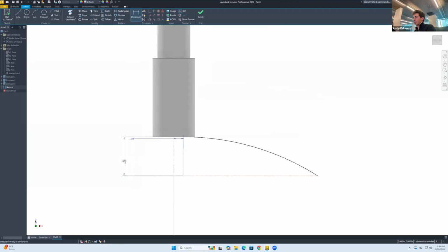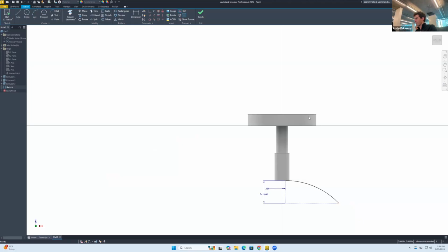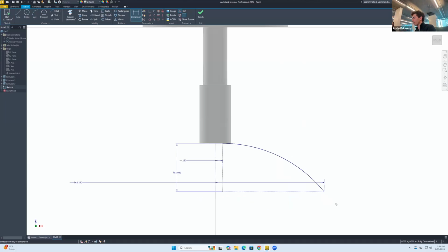Okay, final step, we are gonna make that height times 0.25 this time. Okay, not all of this is black because we need to define how big we want that diameter to be. So if that's dia, we can say that I want the distance from here to there to be diameter times 1. Actually, times 0.75. Let's see what happens. Okay. So the more dimensions that we can reference with respect to those three parameters that we created, the better. And everything else will be smooth sailing from there.